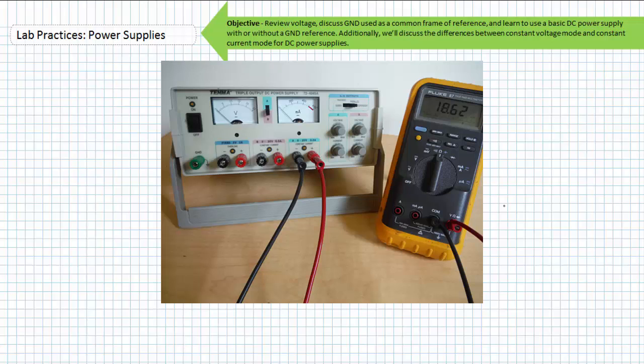It's for this reason all resistance measurements of individual components are taken when the power is off and they're removed from the circuit. Anything still in the circuit with this power supply, even if it was off, would be in parallel with this 18.6 kiloohm resistance, hopelessly rendering inaccurate any values you obtain. One more comment about these resistance values we've obtained using the DMM in ohm meter mode. Notice how smooth the transition from voltmeter mode to ohm meter mode was. At no point do we make the unforgivable error of taking a resistance measurement with the power on.